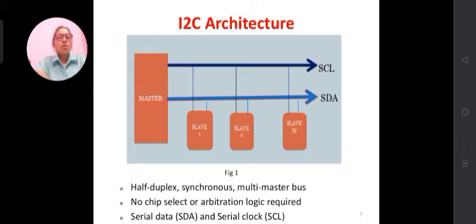There is the architecture of I2C. I2C connects multiple slaves to a single master, and we can have multiple masters controlling single or multiple slaves. This is really useful when we want to have more than one microcontroller logging data to a single memory card or displaying text to a single LCD.